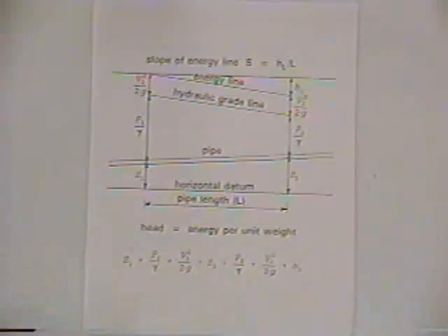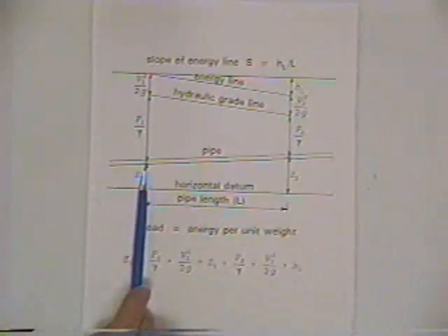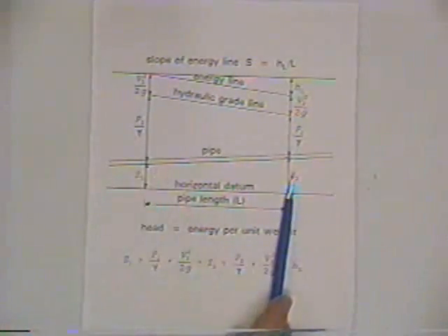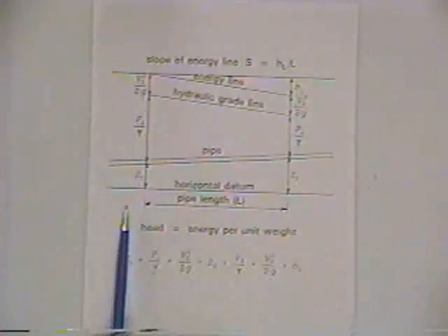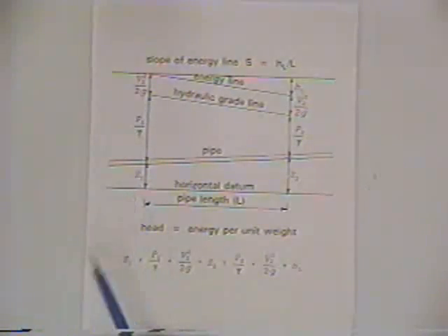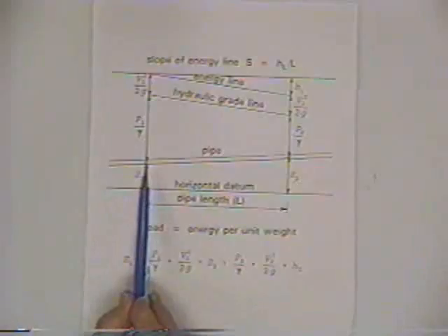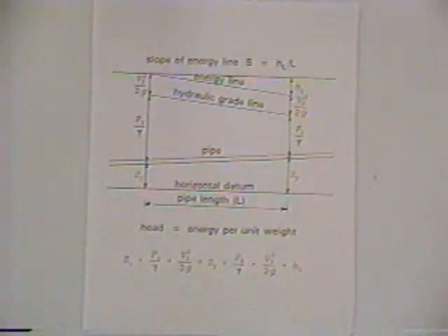And hydraulic grade line, there's a whole category of problems in dealing with hydraulic grades. And so the basic definitions are given here schematically. And again, we've drawn this for a pressure conduit, for a pipe. It could be drawn for an open channel, different types of systems. But basically, we've got the energy at one location, which we're relating to the energy at another location. And the energy is the elevation head. And all of these are in terms of vertical heights in meters or feet. And so an elevation head above a datum.